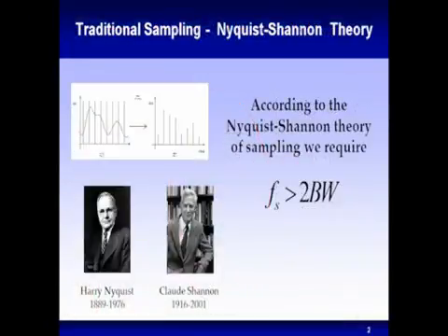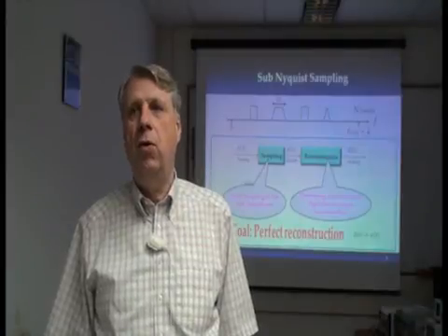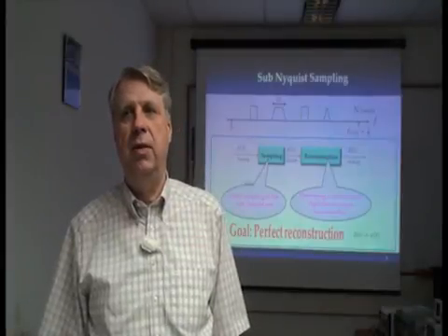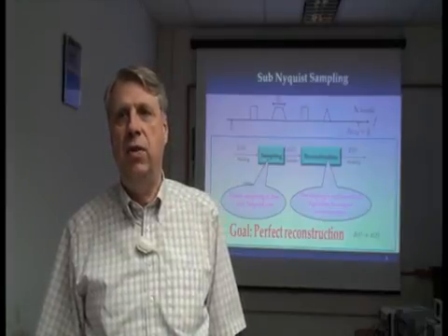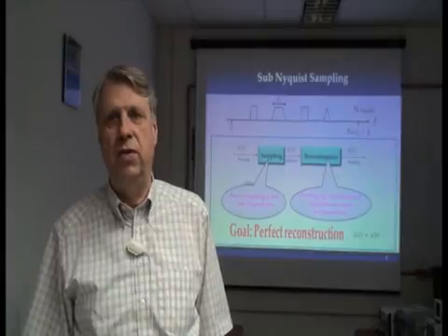The Shannon-Nyquist theorem states that input signals to be sampled need to be band limited, and that for perfect reconstruction, the uniform sampling rate applied must be at least twice this bandwidth. Our goal is to pre-process the multiband signal in such a way that we can sample it at a rate much lower than the Nyquist rate of the original signal.